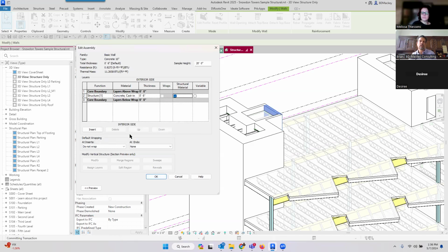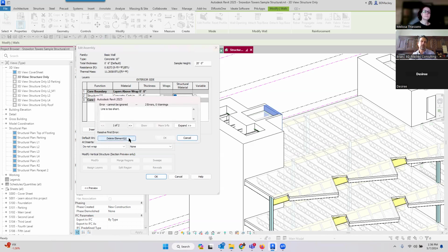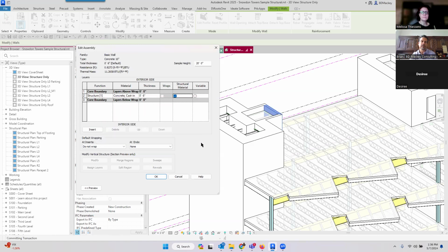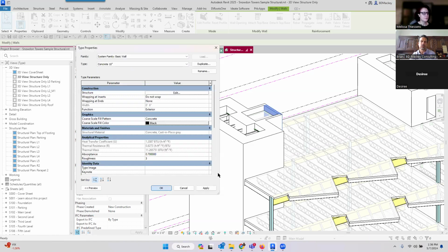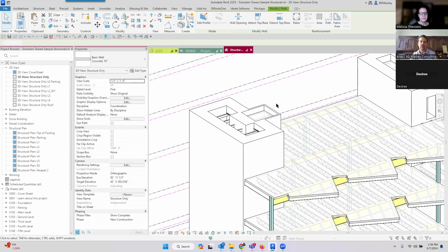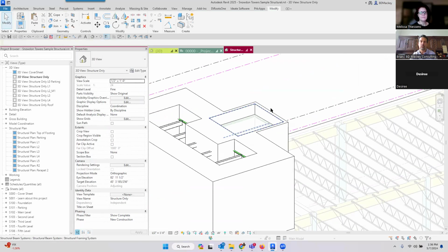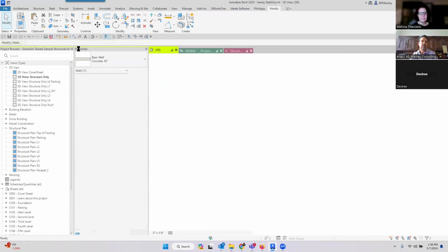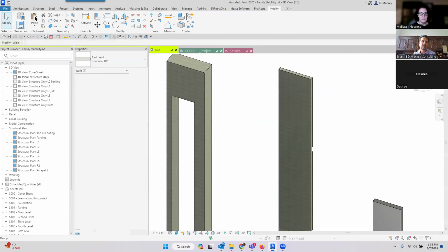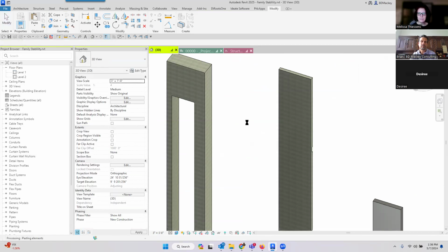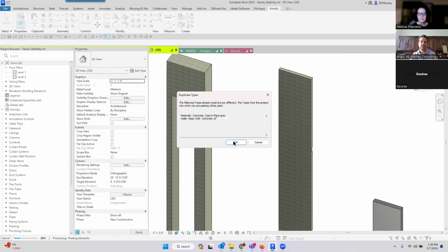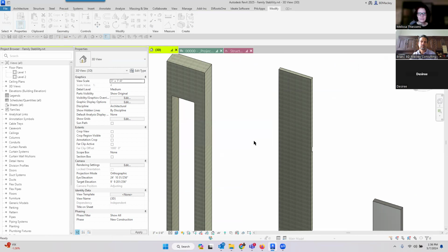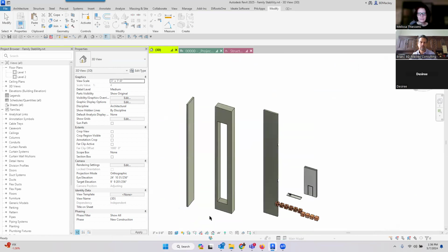The one thing that I really wish, and I know it's been on the Autodesk wish list for a while, is when I do transfer project standards, it lets me choose what I want to transfer, because I might not want to transfer all of the wall types. I only want to transfer that one 6-inch or that one concrete 10-inch wall. Yeah, I've been getting around that by moving my wall types around for all the shop drawings we've been doing lately, saving off a copy of the project I want to use and then just deleting out what I don't want.